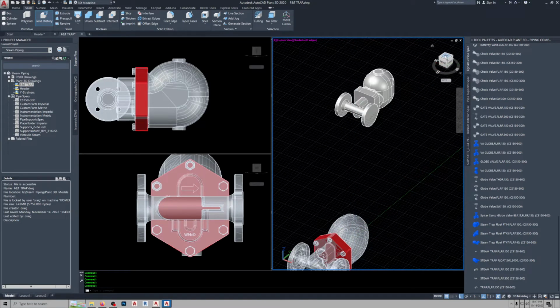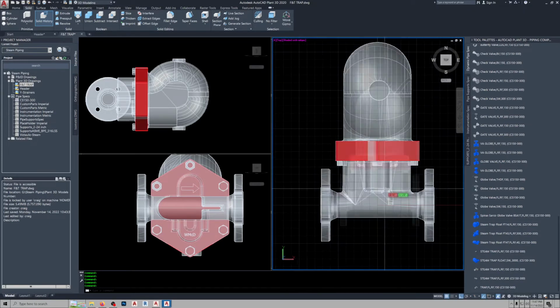Then when you go into the top here, you're going to want to delete everything from there down, so all you're left with is this. Now, you're going to have a big hole in it where all this stuff was, and you're going to have to patch that hole. And once you get that patched, then you're going to have to convert this surface model back to a solid.